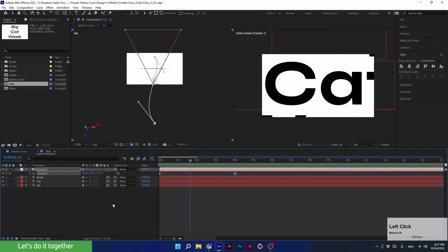We learned how to create a simple camera animation, and now let's try to create a slightly more complex one. But before that, let's delete the current keyframes on the camera. As I mentioned earlier, we need to pay attention to the order of deleting the keyframes to position the layer in a specific place. In our case, I want the camera to be without keyframes and to stay standing where it is standing in the last keyframe.